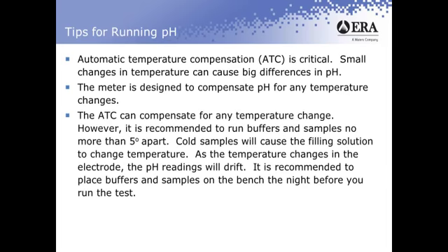However, I would highly recommend to run your buffers and samples no more than 5 degrees apart. And here's why. Cold samples, or a sample of a temperature significantly different than what you're running your buffers at, will cause the solution inside your electrode to change temperatures. As that temperature is changing, the pH meter is trying to adjust your pH value for the change, and it never really stabilizes properly. So again, if you know you're going to run pH tomorrow, place your pH buffers and your samples on the bench the day before you run that test so that they'll be at consistent temperatures.